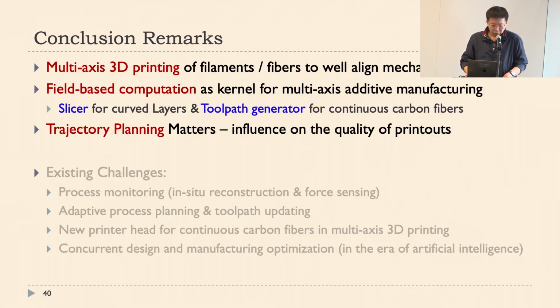And so, in conclusion, today I covered multiple axis 3D printing, which is able to help you align with the anisotropic mechanical property inside of the field very well. So we're using field-based computation and slicing and toolpath generation, all based on field representation.